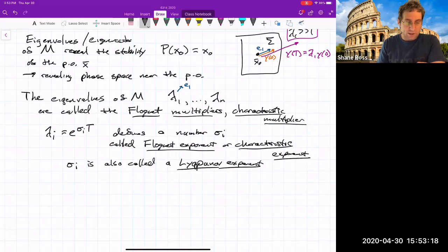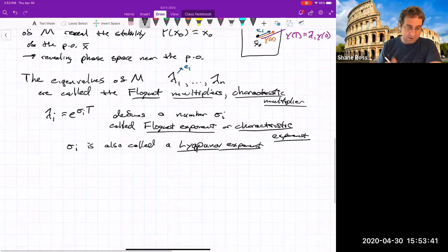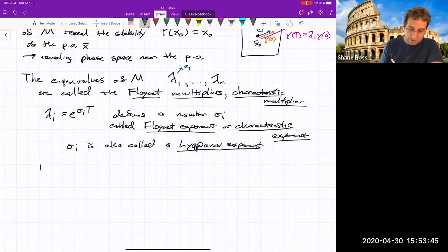Now, where the analysis of the eigenvalues differs from what we might be used to from a continuous system: for a continuous system, you look at eigenvalues in the right half plane or the left half plane. Because this is a discrete system, we're looking at a map. Right half plane, left half plane doesn't matter. It's the unit circle that plays the key role now.